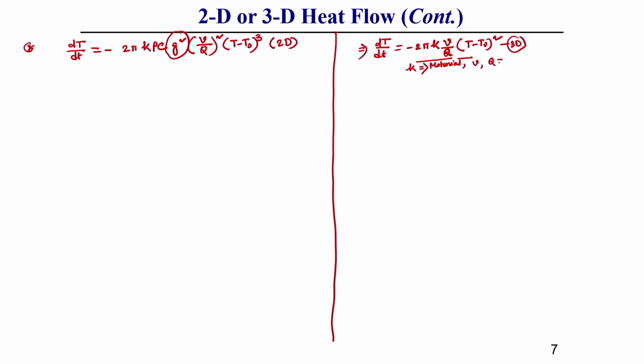What is heat input? It is generally the net heat input, eta V I in watt; its unit is watt, always keep this in mind. What is V? V is welding voltage, I is welding current, and the welding velocity is in meter per minute or millimeter per second, whatever it is.